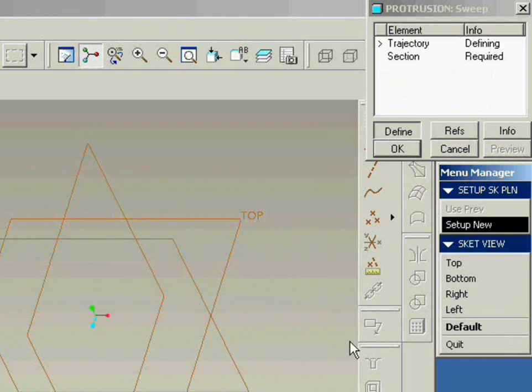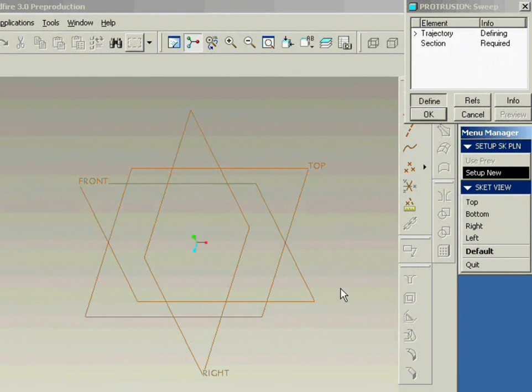I told you that to define the reference and orientation, you can first choose the orientation option from the list, and then you have to select the reference plane from the display area. Or you can go with an option called default, and if you go with default, the system itself is going to define the reference and orientation. Now let me go to default,